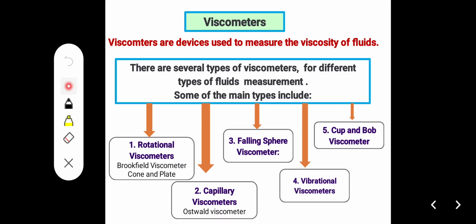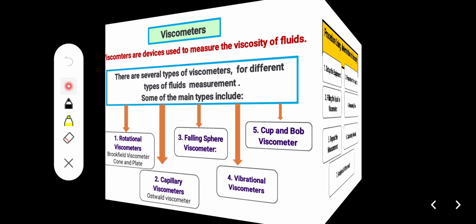Non-Newtonian fluids include plastic, pseudoplastic, and dilatant. Plastic includes ointment, gel, and cream. Pseudoplastic includes natural and synthetic polymers. Dilatant includes deflocculated suspension and paste. Plastic flow shows shear thinning, and dilatant flow shows shear thickening. So these are the types of fluid.